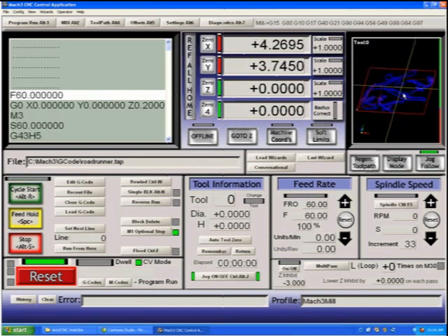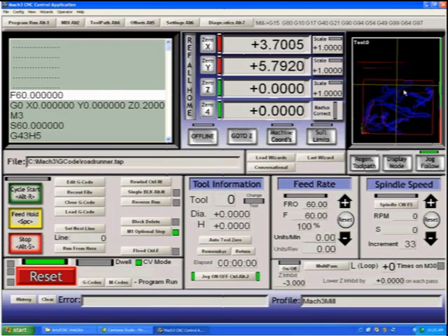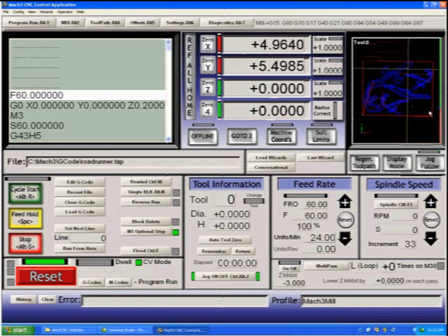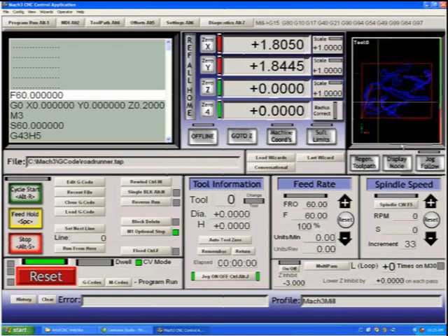Now, whenever you zero DROs, these are the DROs, by the way, digital readouts, these two yellow lines show the X and the Y axes intersecting. So at this moment, my tool is centered somewhere up around this Roadrunner's foot. If I jog my axis, you can see that the drawing moves to show where the tool is currently at when I'm in Jog Follow mode. If I turn off Jog Follow mode, the lines move to show you where you would be. Again, double-clicking will reset the system.